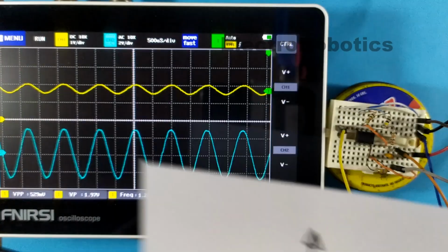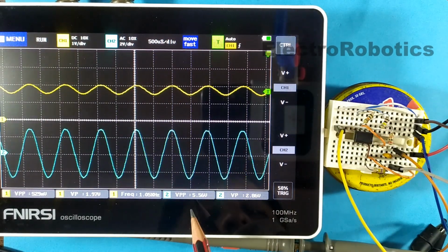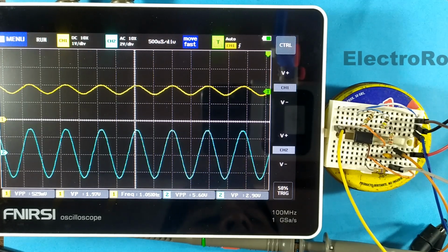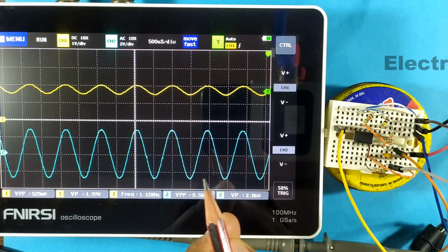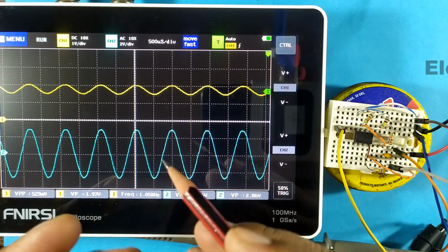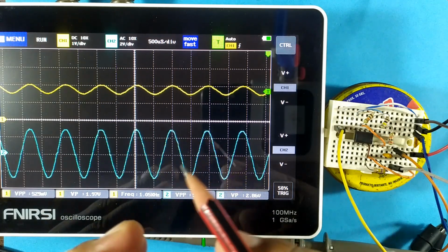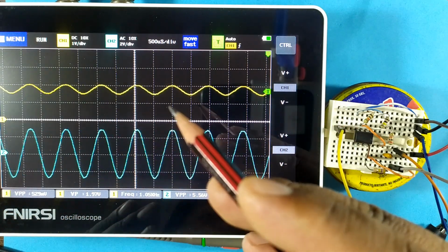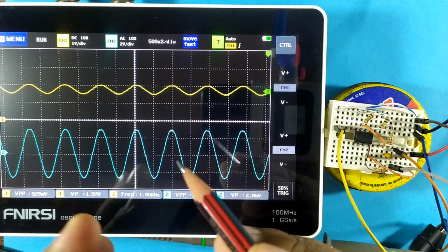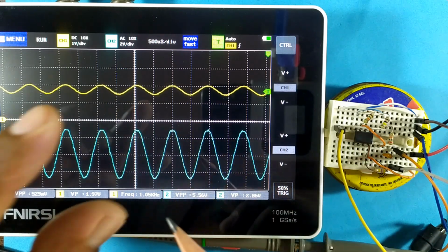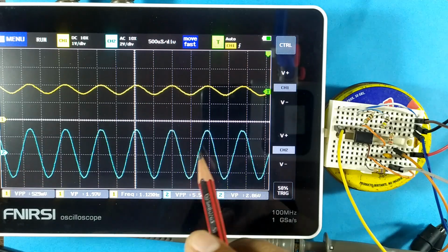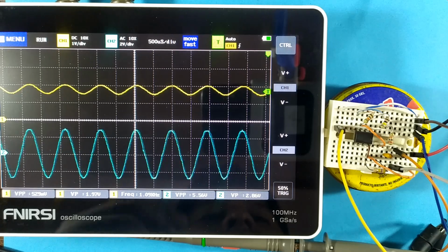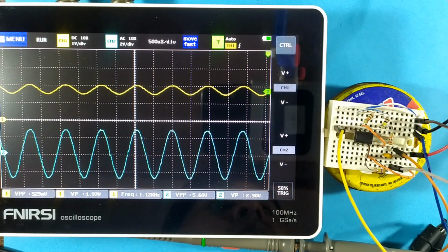So as I am delivering 500 millivolts on my output here, you can see that I have 5.6 volts. I am working with a 12-volt source, so I could still amplify until I get almost to the extremes. From 0 volts or negative to 12 volts or positive. I never have to get close, but I do get slightly close so that the peaks and valleys of the signal are not clipped. Well, this is how the op amp works as a signal amplifier.